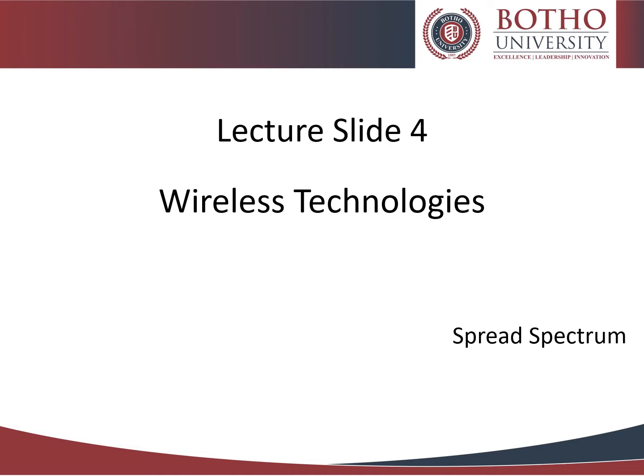In telecommunication and radio communication, spread spectrum techniques are methods by which a signal, it could be an electrical, electromagnetic or sound signal generated with particular bandwidth, is deliberately spread in the frequency domain, resulting in a signal with a wider bandwidth. These techniques are used for a variety of reasons, including the establishment of secure communications, increasing resistance to natural noise and jamming, to prevent detection, to limit power flux density, and to enable multiple access communication.